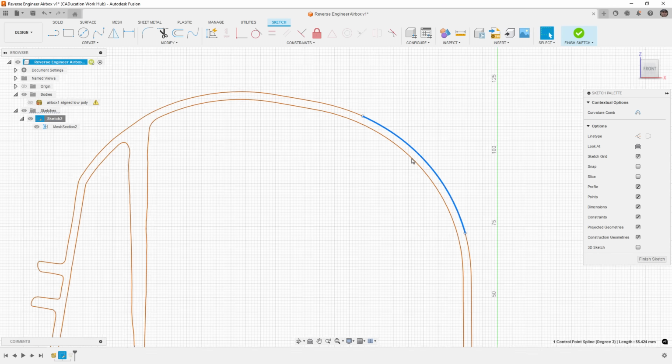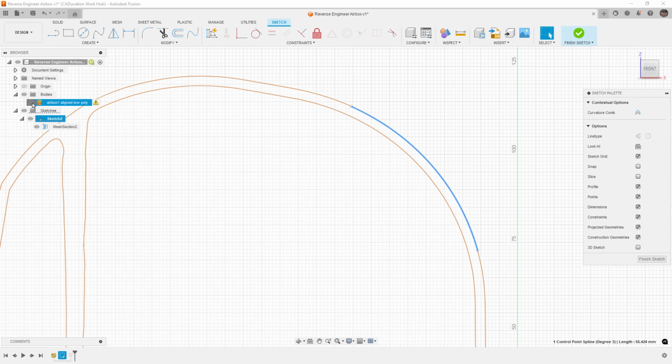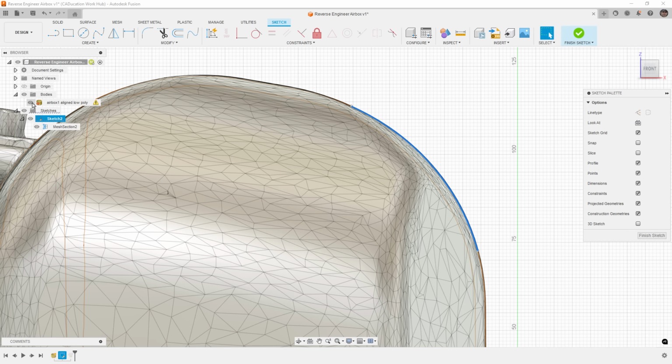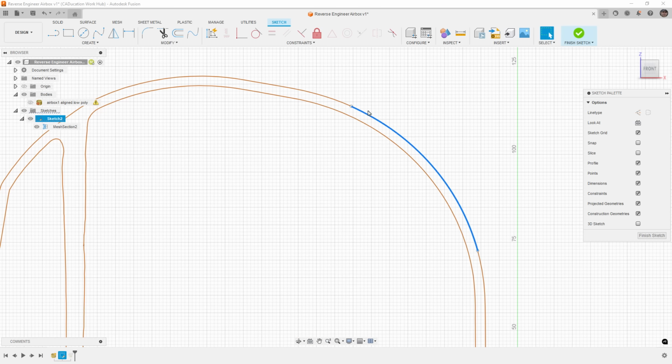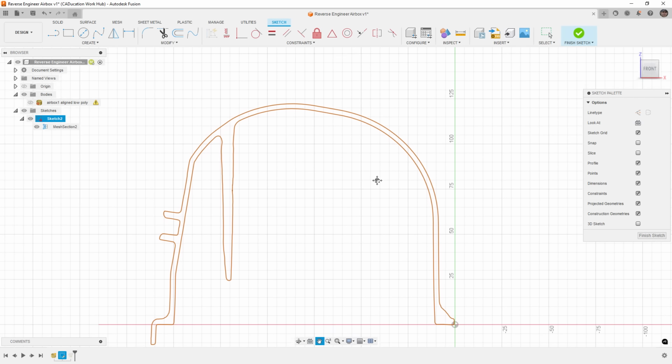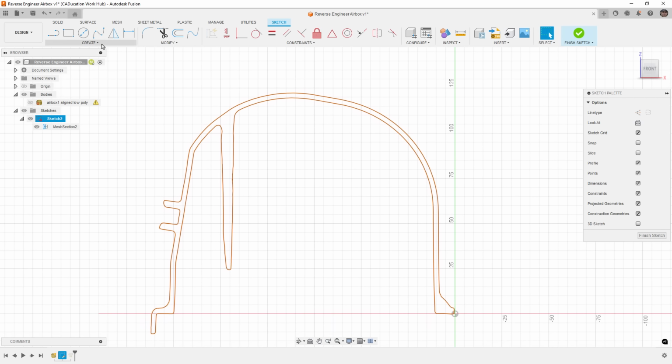And again, the reason for this is because at the core of this, what we're looking at is a bunch of little flat triangles. And so to try to fit a curve or a mesh to that means that we're going to have some of those irregularities in here. So in general, I will not use a spline in a mesh section sketch unless I have a very good reason to. As a reference would be okay. But it is pretty good with doing things like straight lines.